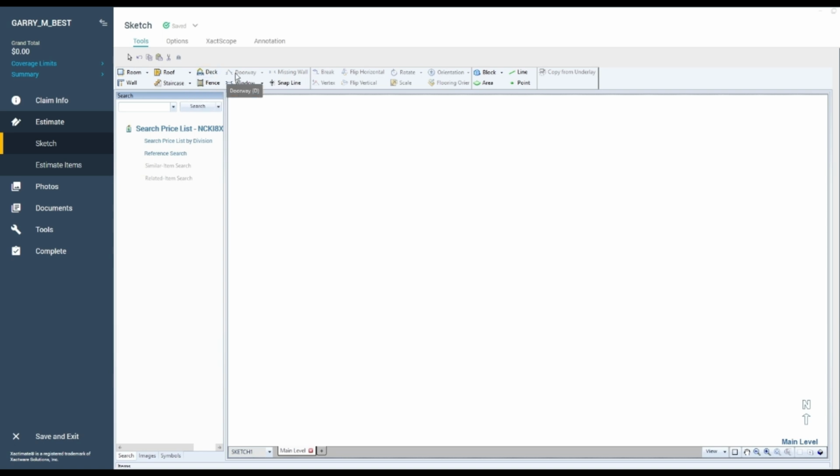We'll start with the Room tool. You can either select the tool from the toolbar or use the keyboard shortcut, R. Once you have selected the Room tool, you can simply click to drop the room in or click and drag the room to size. I suggest clicking and dragging the room to the approximate size, as you can edit the dimensions easier once it is placed.